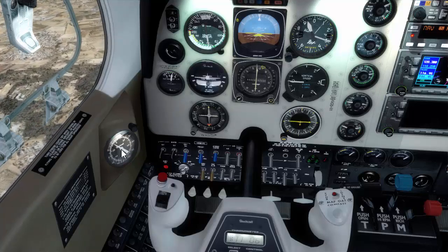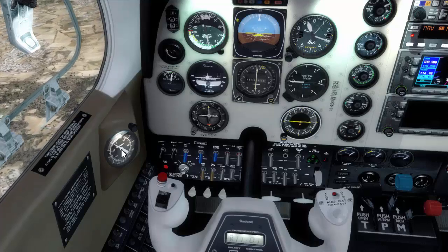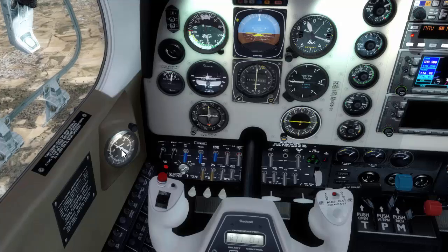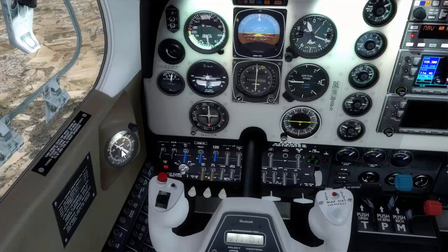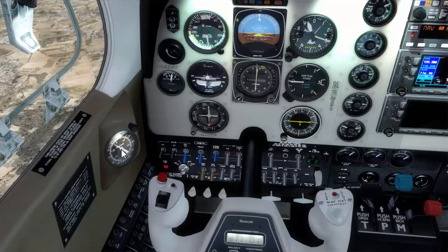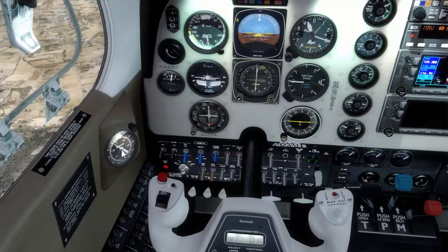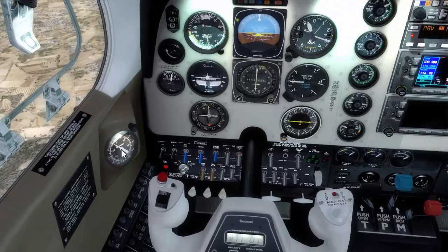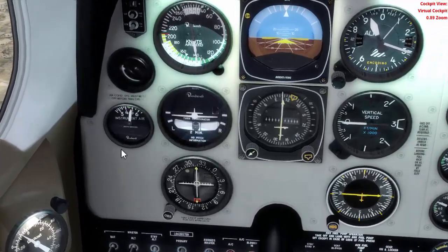By the way, when you see a black triangle, it says that it is a compulsory notification point. That is that you have to contact the ATC, and when the triangle is white, it is that you are reaching an airway, but you are not forced to contact the ATC. Okay, so when you see a black triangle, it is a compulsory notification point.